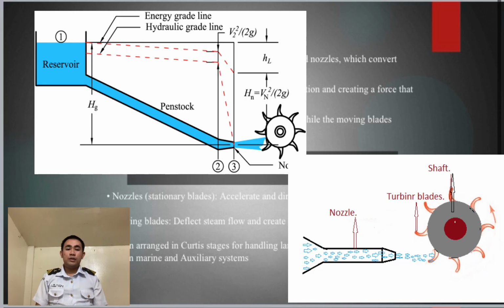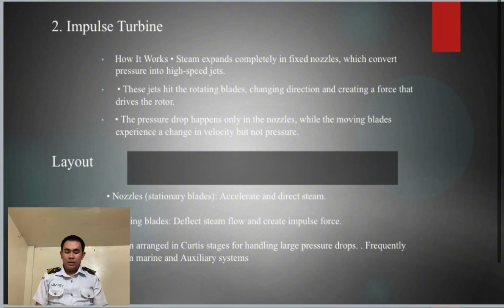As you can see in the diagram, there's a label named penstock, from which the water comes. The water flows directly to the nozzle, and the spear regulates flow into the bucket-shaped runner, which then directs the used water to a tail race.